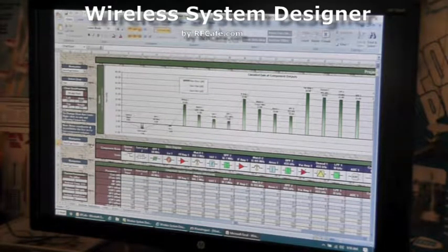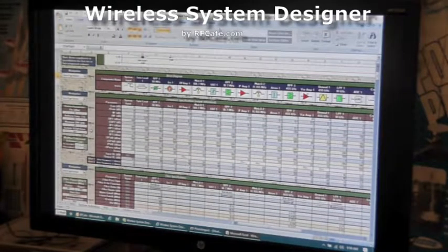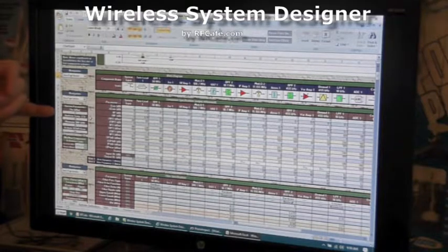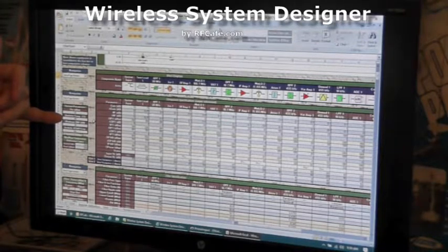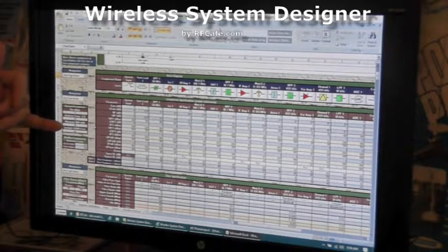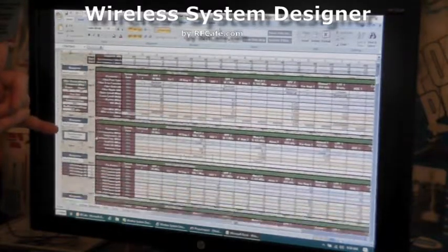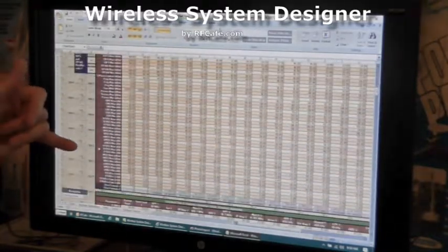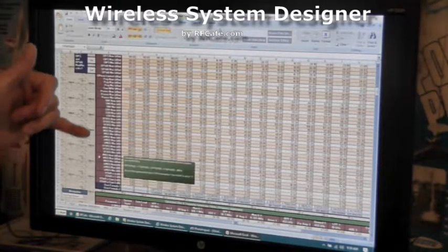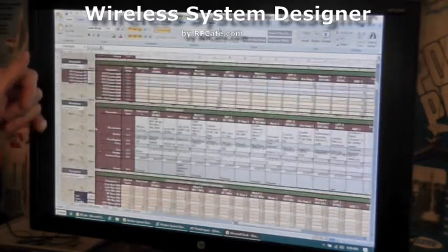Again, it's just a convenience feature. Coming down here, the input system overall parameters I have, you set your input power down here, what your temperature is, that'll affect the noise calculations. Minimum signal to noise ratio, that'll affect down here later what some of the other parameters are.